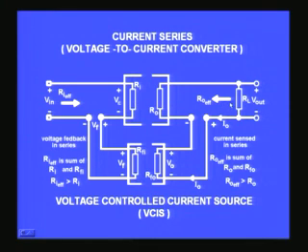So what is the effect of that? Because the output impedance is increasing, this becomes a current source. It is not a voltage source, because only for a current source the output impedance is very, very large. Usually for an ideal current source it is infinity. And at the input the resistance is increasing, that means the input will have to be a voltage. So you have a voltage at the input with a large input resistance for the effective amplifier, and you have a large output impedance corresponding to a current drive at the output, and therefore it becomes a voltage to current converter. Input voltage will be converted into a current by this feedback arrangement, or it also can be called a voltage controlled current source, VCCS.